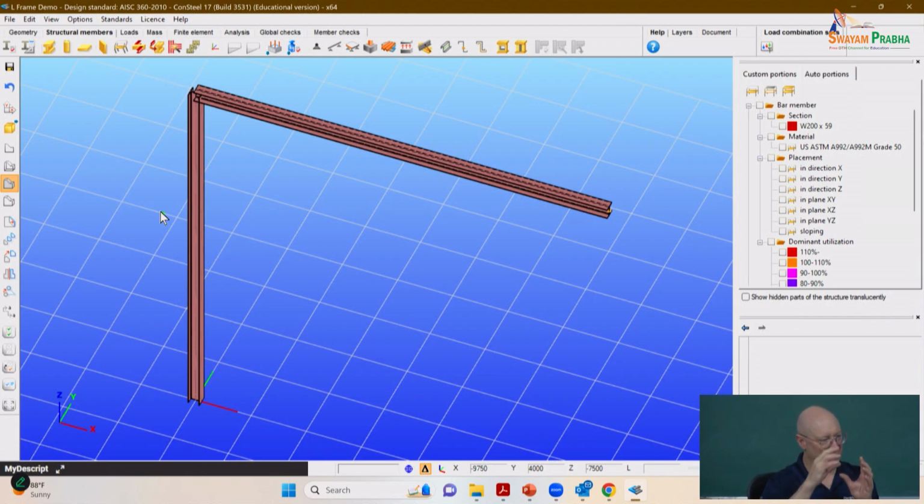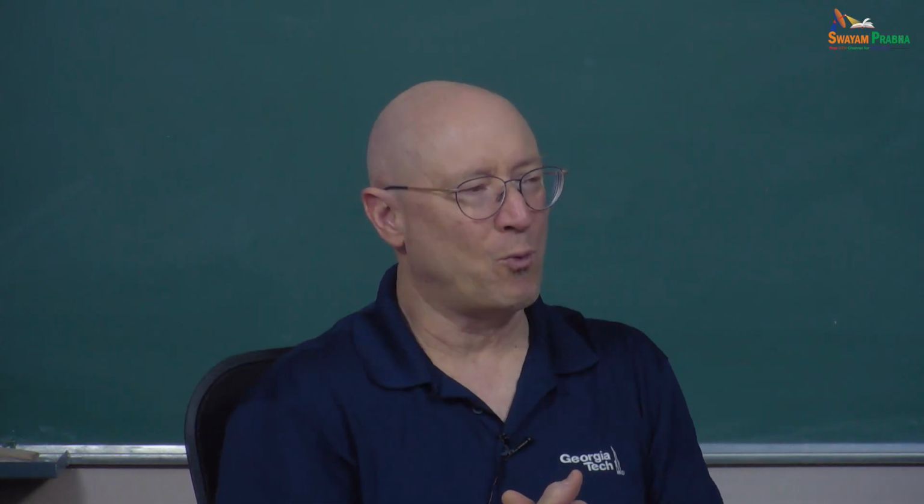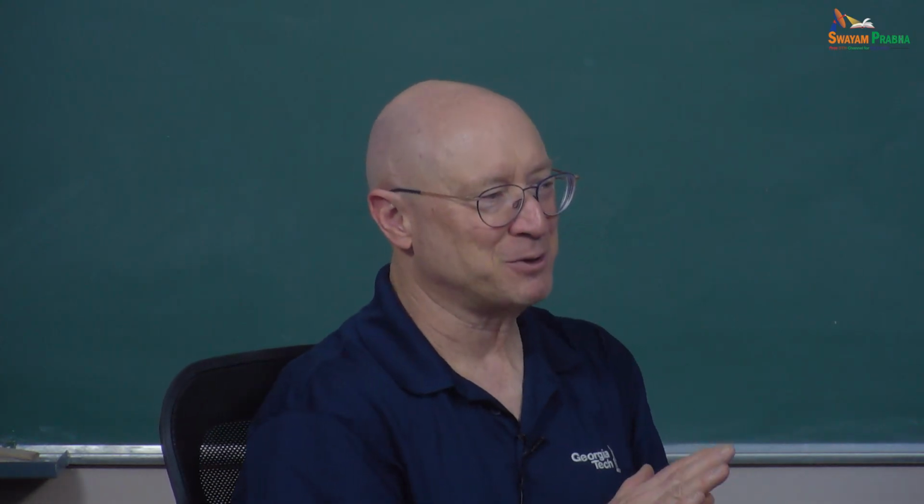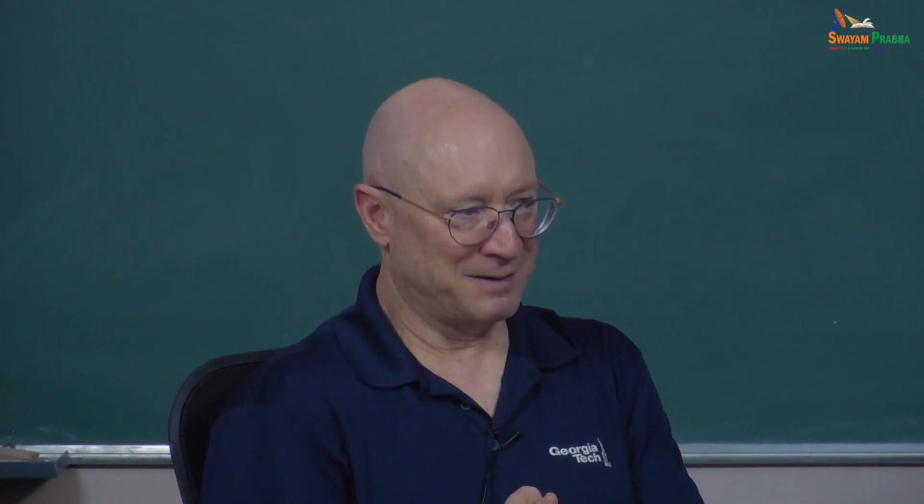Basically, it models different types of details at the joint: how does the warping continuity transfer through the joint? It's basically a thin-walled open section beam approximation of what you could get if you actually ran a shell finite element analysis at the knee. How critical is the warping degree of freedom in these calculations? Warping is essential when it comes to stability of thin-walled open sections. In the discussions we have had, we have not included it.